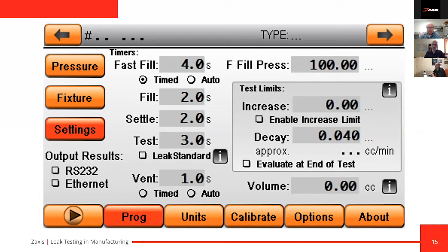Tracer leak is typically 1 × 10⁻⁴ or more. 1 × 10⁻³ is about the limit we do, but that all depends on the product and the size, and there's a few things we'll talk a little bit about. But yeah, 1 × 10⁻³ per second is about as low as you'd ever try to go with a pressure decay test. Yep, cc's per minute, I see that.